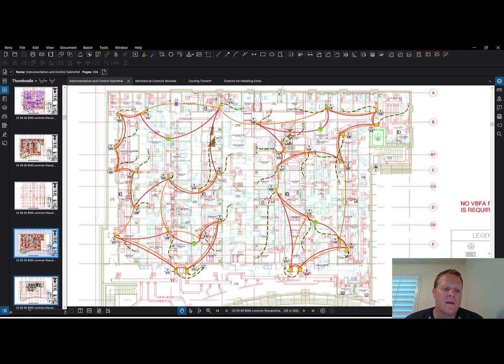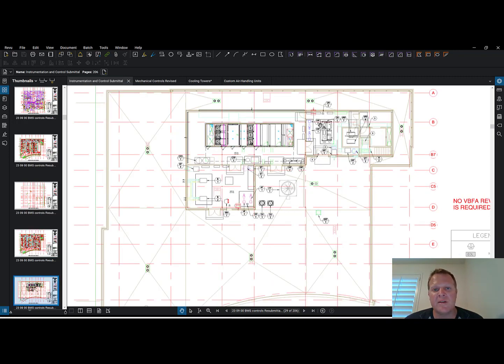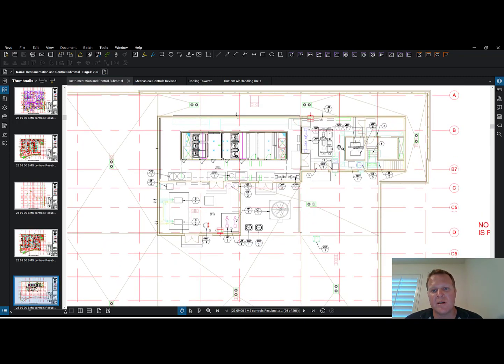I think it's a good thing if you're asking, as a general contractor, to follow up on components. Tell me about the status of the chiller. How much more work do you have before it is operational? What status are we at with the startup, that kind of stuff? Or the same thing with the boiler. Have we flushed, filled, and tested the boiler piping yet? Is the boiler operational?